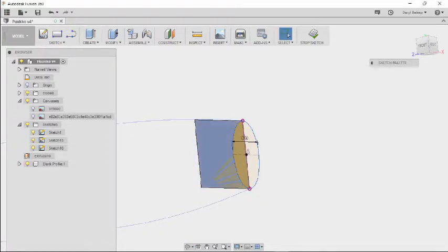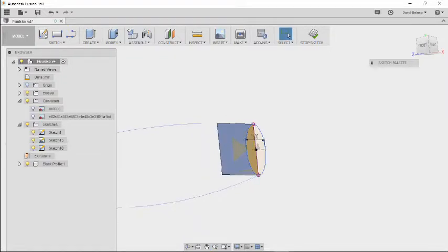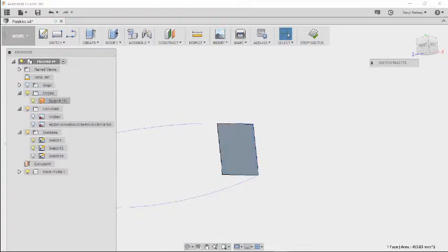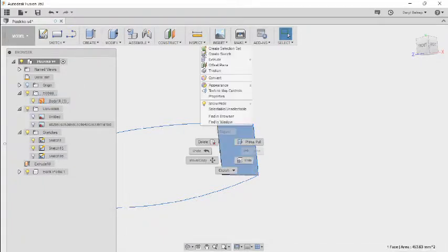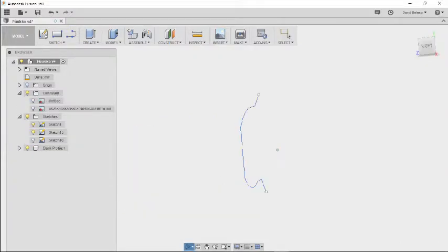When you see streaky like that, that means you're on top of a sketch with a body underneath it. So we're going to turn this sketch off for just a second. I'm going to select that and delete it. Let's see. I'm selecting that. Oh, I'm still in the sketch. So I got to stop the sketch first. Select that. Now I'll turn the sketch back off because it came on when I stopped it. Select that body and delete it because we're done with it. It was just in the way now.